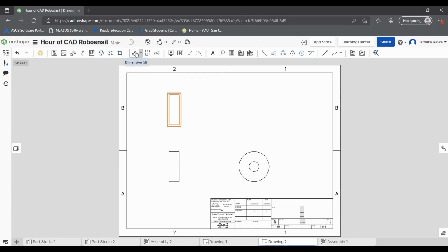So as I mentioned, some of the things you can do are set dimensions. So I can click on this outer radius and define 1.5 as the diameter, and I click the inner radius, define half as the diameter, and I can define half as the thickness. So yeah, those are some useful tricks. You'll see all these other things here. You can add notes, you can add tables, BOM tables, whole tables, really anything that you think might be useful.